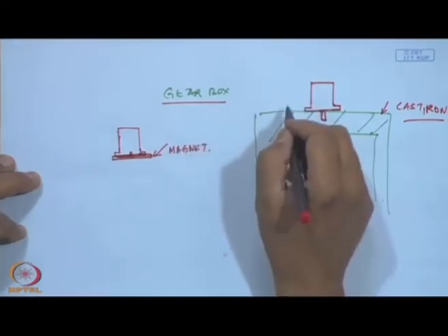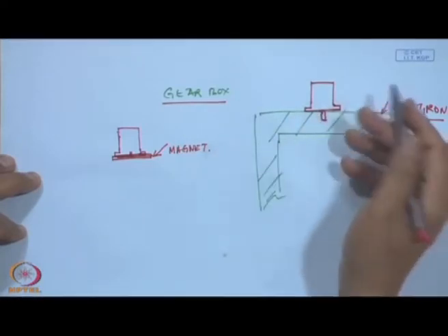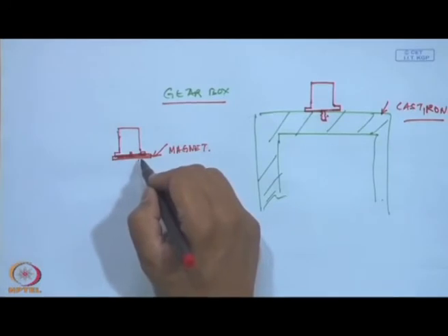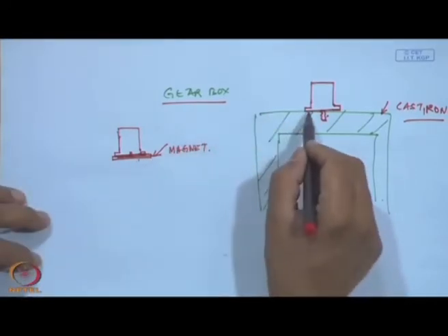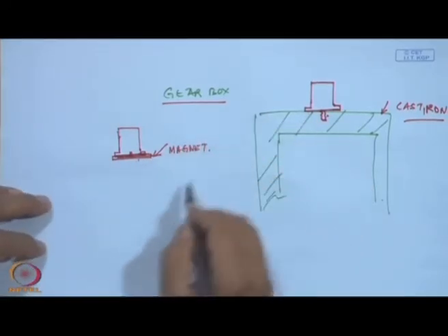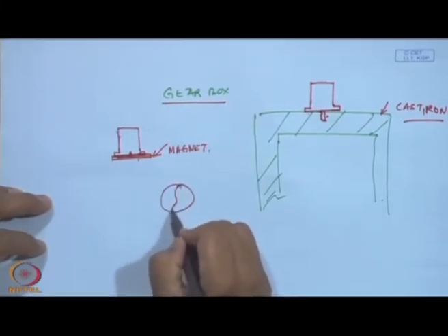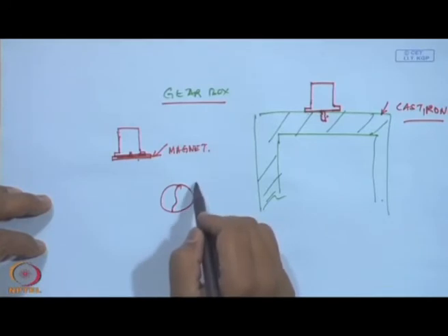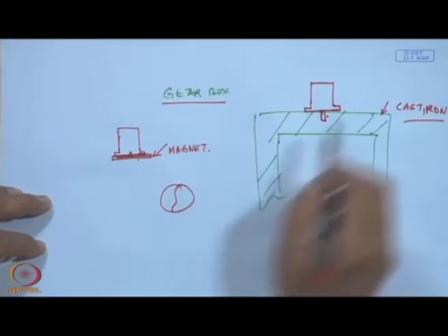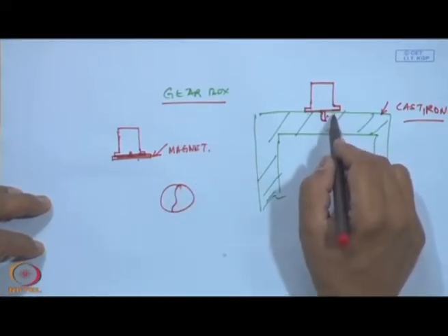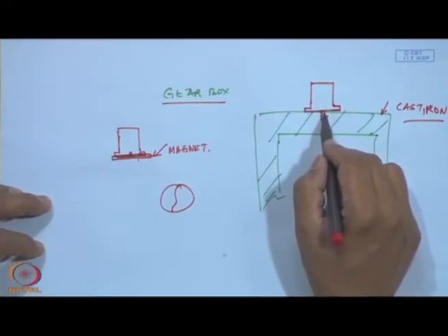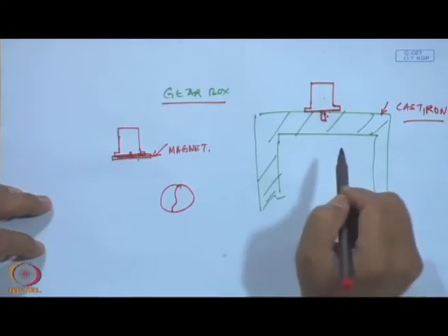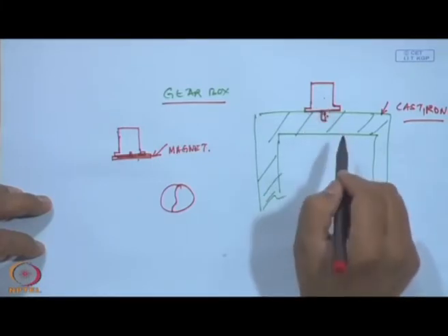Okay. But again out of my experience I am telling you, these soft magnets are very soft. These magnets cannot be subjected to high temperatures, with time suddenly you will see that the magnet has cracked. So, usually these magnets cannot withstand high temperatures. So, usually if you have to mount permanently, you make a hole and put a stud, and then you tap the accelerometer onto it.